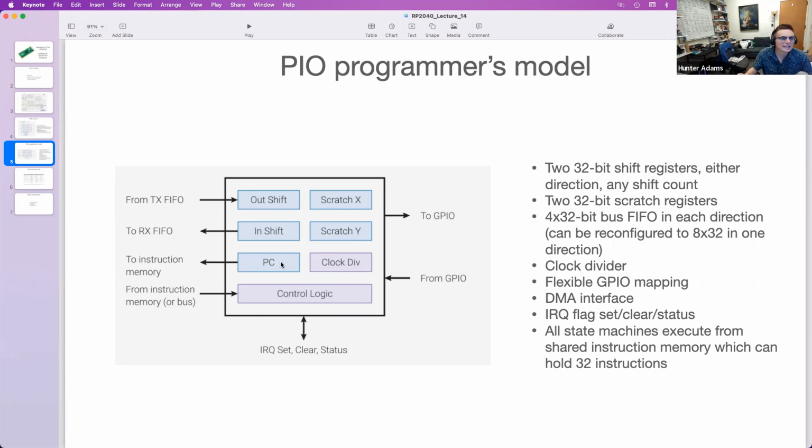As we'll talk about in more detail today, and as we talked about last time, there are instructions in the instruction set for these PIO coprocessors that allow you to conditionally move this program counter. You can execute a jump. So you can jump from one instruction to a specific instruction further up in the program, or alternatively you can jump over a bunch of code to some instructions that are further down, right? So you can use these jumps to jump around the program.